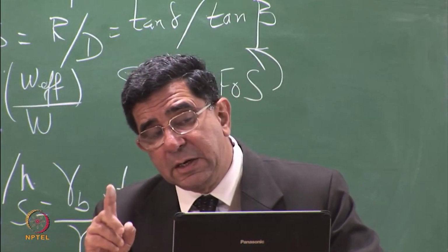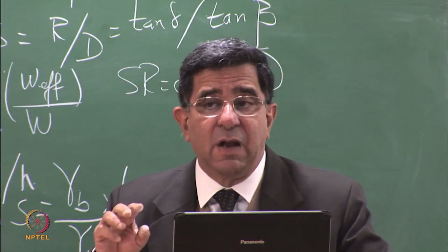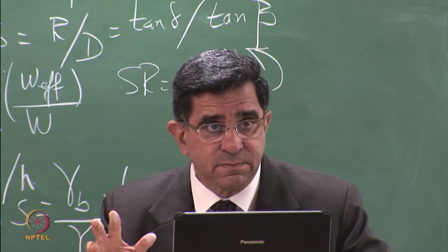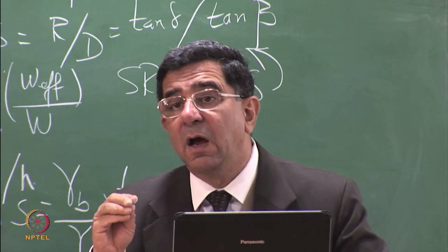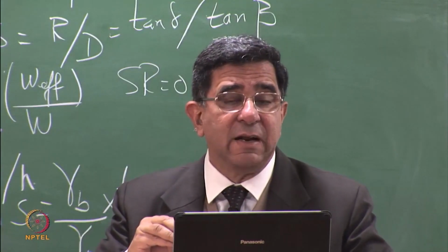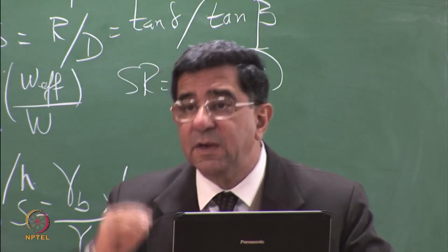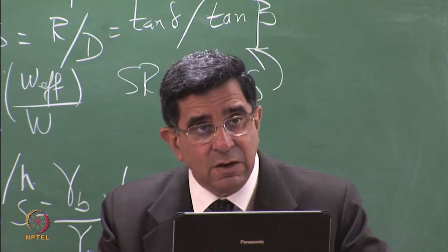The difference between seepage case and earthquake cases, an earthquake will last for a few seconds. So it is a dynamic phenomenon which we can do the analysis in a pseudostatic manner, but we can have the factor of safety, acceptable factor of safety, fall down to a much lower value.